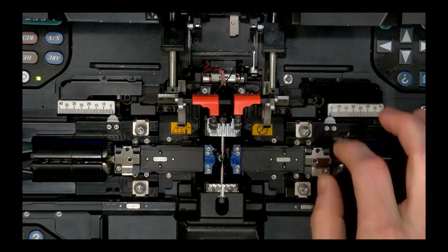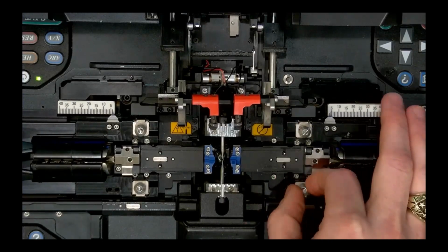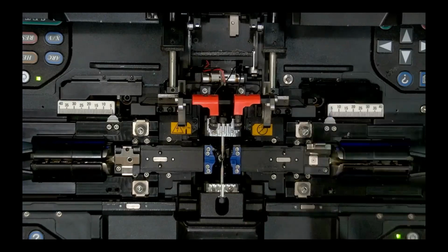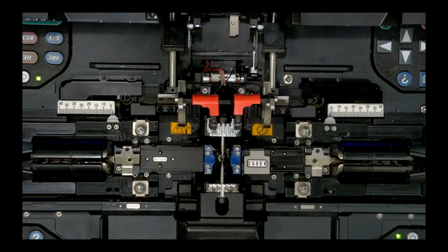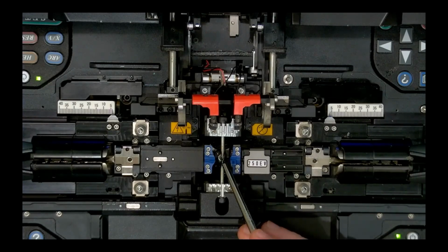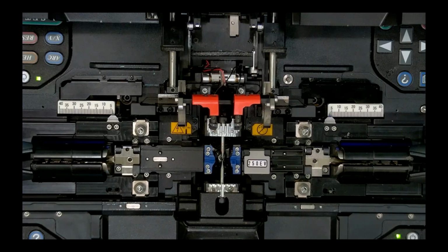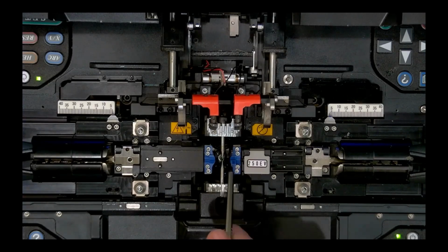And the last thing, or actually second to last thing, two more things I want to mention about this is what you just saw me open. That is the end-view LED unit. Right? So you can see the fiber image, right, by having a mirror there, but you can't see anything if it's not illuminated, right? And so what this LED does is it'll shine a very bright light on the side of the fiber to inject light into the fiber, right? And then let some of that couple with the cores and let some of it be guided by the cladding for this short distance so that you have an illuminated image on the actual cleaved end of the fiber.